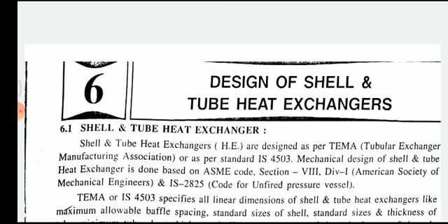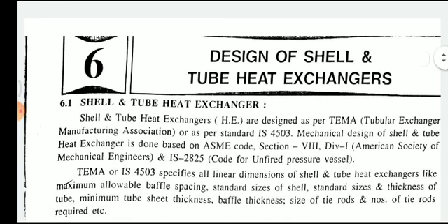So shell and tube heat exchangers are designed as per TEMA or as per Indian Standard 4503. And mechanical design of shell and tube heat exchanger is done based on ASME code, the American standard, American Society of Mechanical Engineers, and Indian Standard 2825 for unfired vessels. So this coding is important for the designing and the standard design.